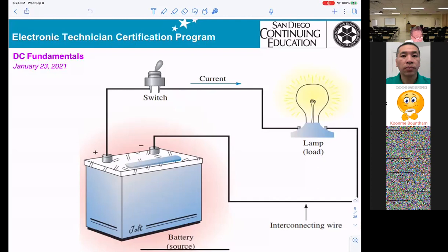Okay, but we're working with what they call a conventional current. Conventional current, all the time, they will be drawing going from positive to the negative. Okay, so I am telling you that way. The thing is, when you are reading the textbook, most textbooks draw the current the other way, from right to the left. That is they draw electron flowing. Okay. However, we deal with the conventional current. Make sure you understand that. It is the same current, but flowing positive to the negative. Okay.